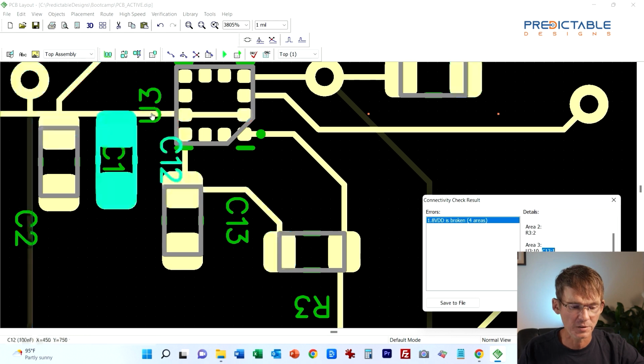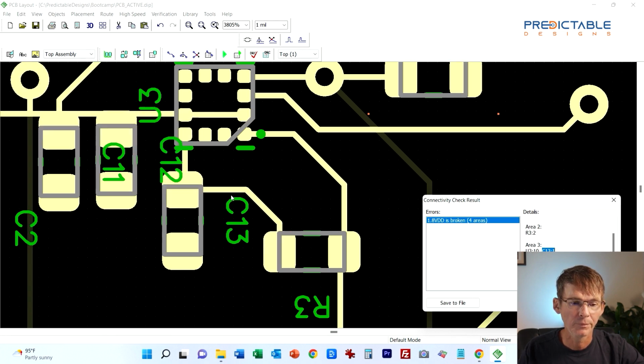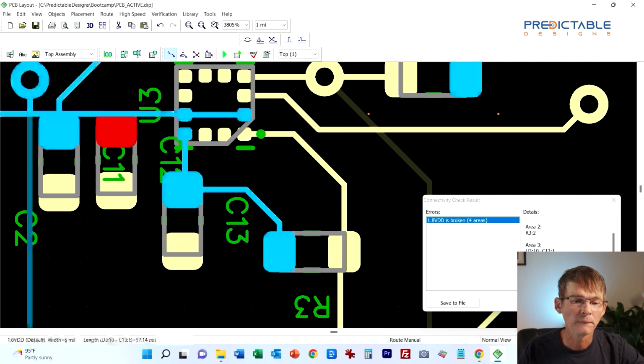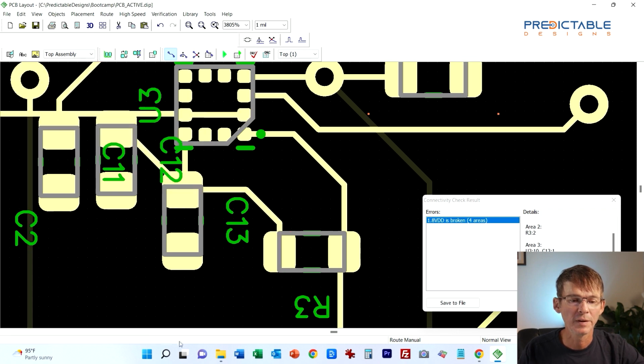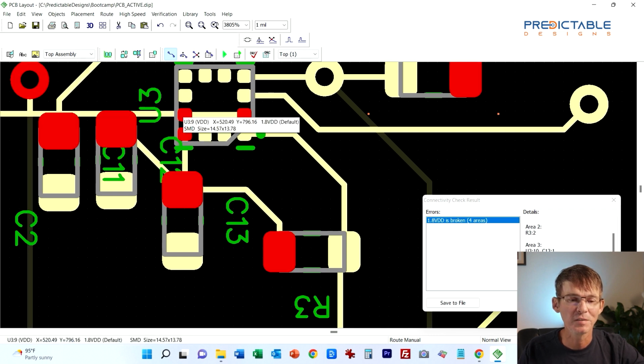So now I'm going to just connect, let me just, and we'll just tie that there. This is the VDD IO for the accelerometer, and this is the normal VDD. They're the same on this design, so I can just tie this together.